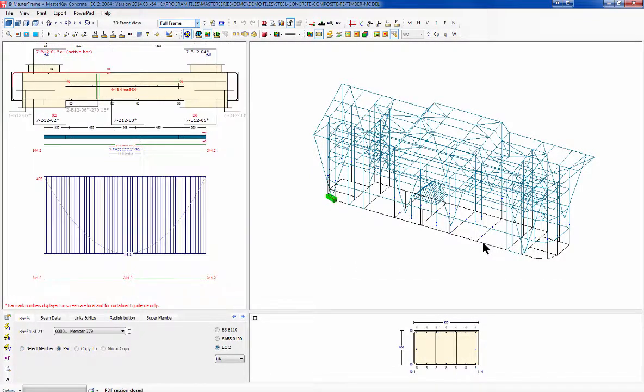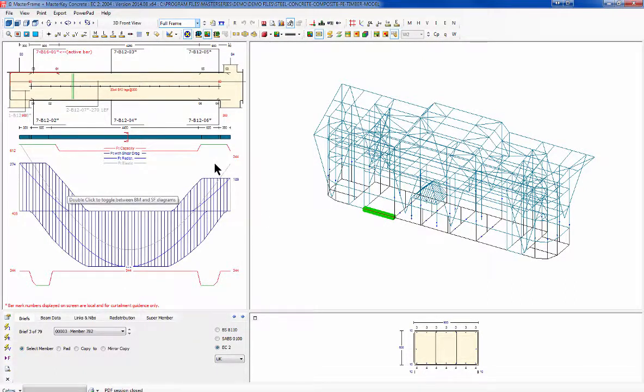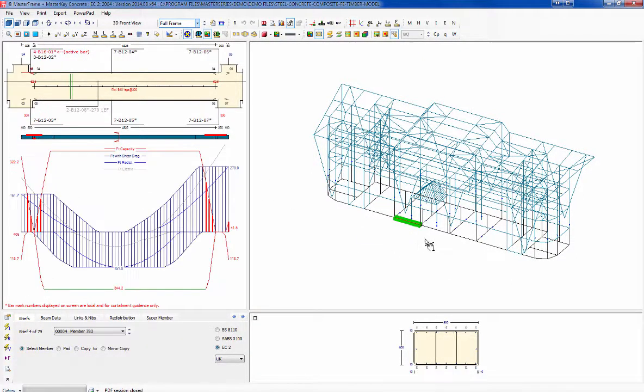So I can look at a beam and I can see the reinforcement working pretty good on this beam. And I can see the reinforcement here on this with redistribution all working. And it's very straightforward. If you start to reduce your reinforcement by using your mouse, it will show you the failures as you design. But I can say make this all fail and then just say go on, you try it, and it comes back up with 8/12 is satisfactory at this location.